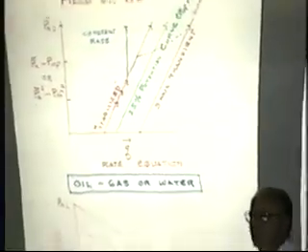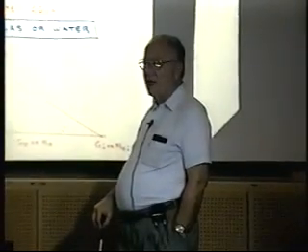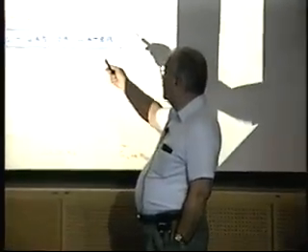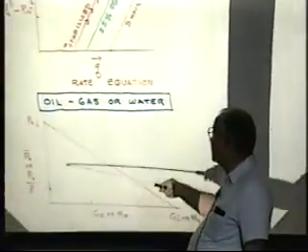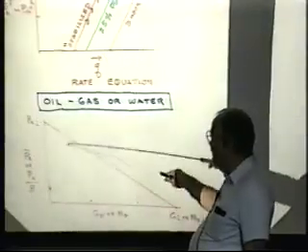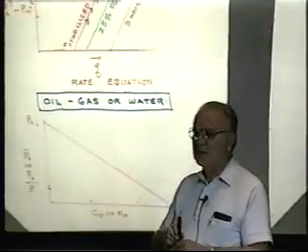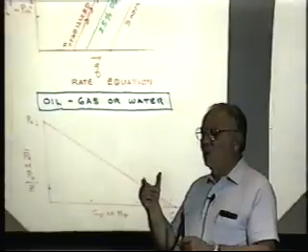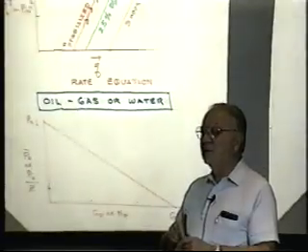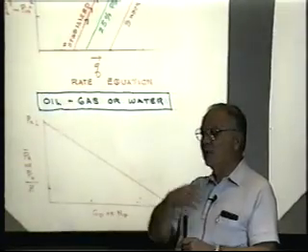I don't know how many of you use program 7151, the gas production forecasting program. All it takes is input of the variables for a stabilized curve and a gas in place, and it just works back and forth between the rate equation and the material balance equation on a monthly basis to get a production forecast. Does anybody here use that program? We've included in that program the ability to handle layered no crossflow reservoirs, where there is no crossflow between layers. You can put any number of layers in there.